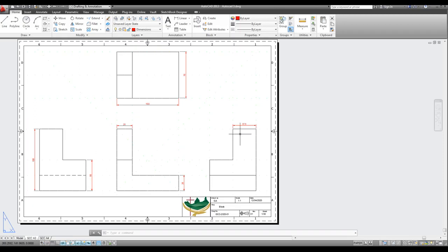We've got this dimension here that's height. This one here, we wouldn't put this dimension on here because that being 37.5 on the width, and we've got the width here, it's obvious that this one would be 37.5 as well. So you don't put two dimensions on that add up to another dimension. That would be called a closed dimension. If you ever do that, this dimension here has to end up in brackets. Because if these are a little bit wrong, then that dimension won't be right.